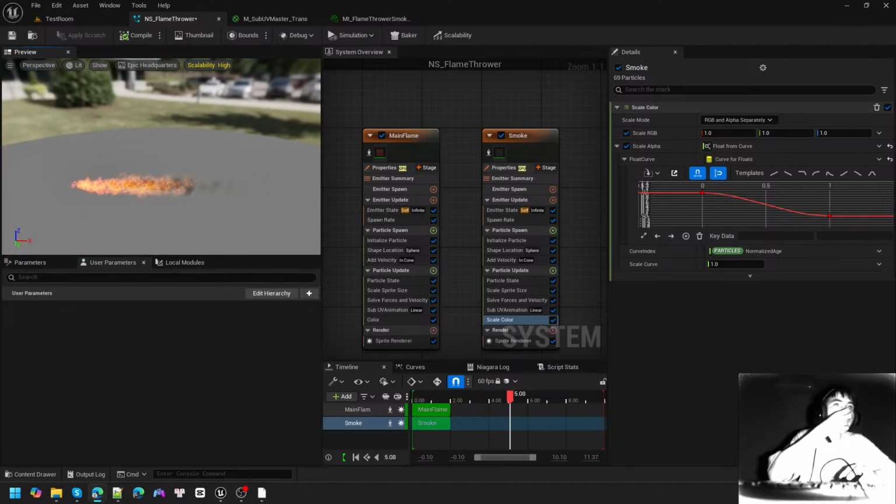level. Right now, I can barely see the smoke, so I'm going to adjust the scale color curve a little bit. So go back to this flamethrower. So I'm going to select the start time of this fading. Now, instead of 0 seconds, I'm going to set it to be 0.5. So that I'll have more black smoke before